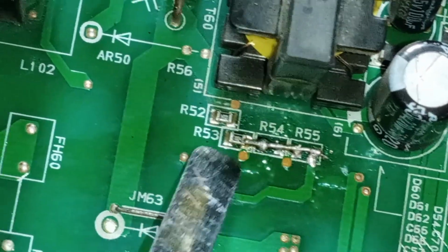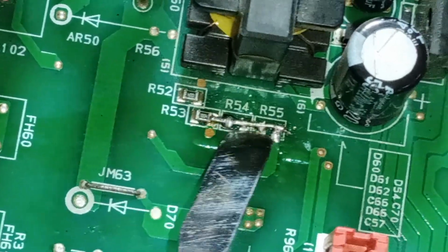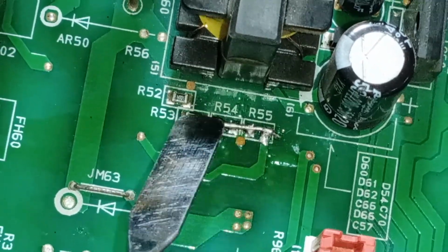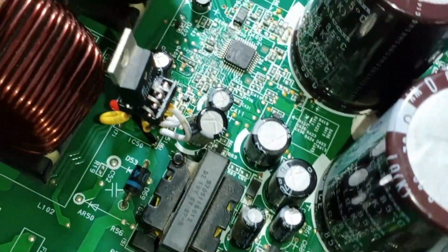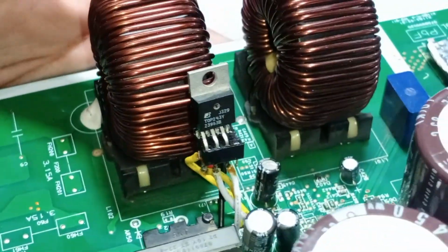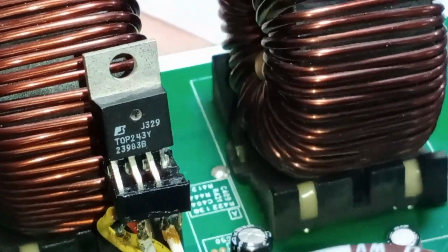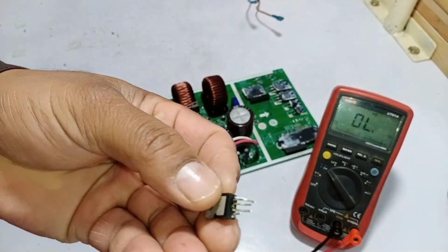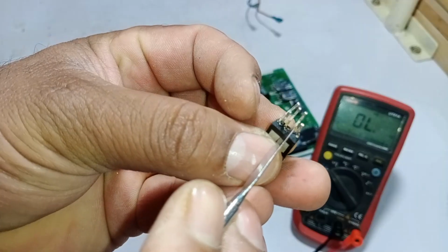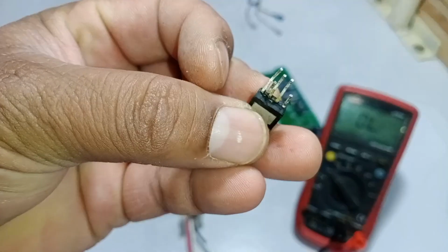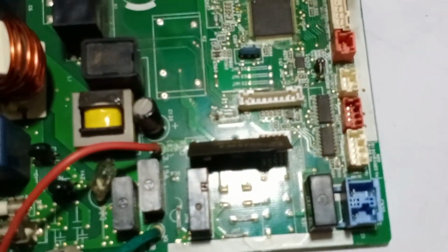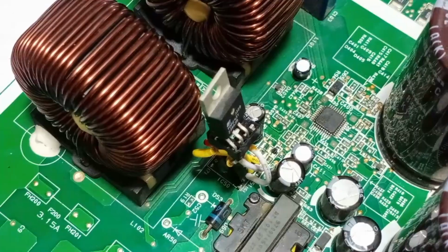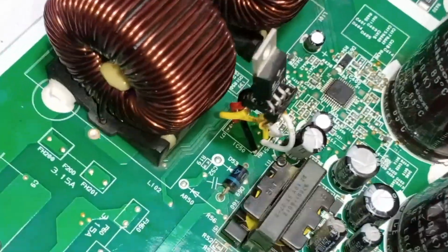As you can see, I removed the 2 megaohm resistors and replaced them with jumper wires. This adjustment ensures the desired configuration, and you can do the same if needed. Regarding the IC, I made a slight change in the IC number, but the family remains the same. Let me explain why I did this. The previous IC developed an issue as one of its pins, specifically the 4th pin, broke during handling. To proceed, I used a different IC from the same family for testing purposes. Now the unit is operational, the indicator light is on, the switching is functioning correctly, and all the IC wires have been set properly according to the circuit requirements.